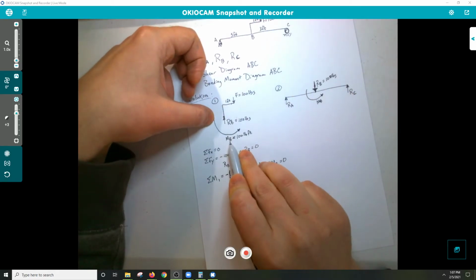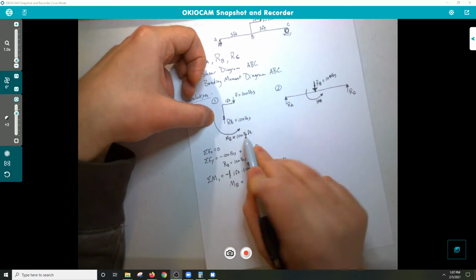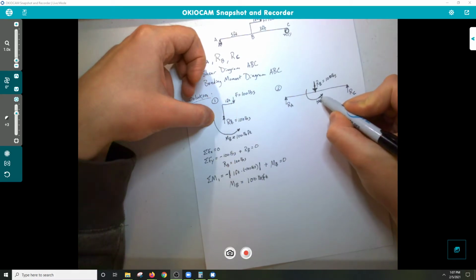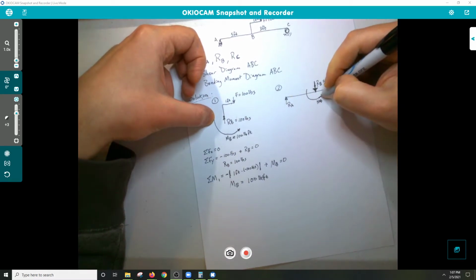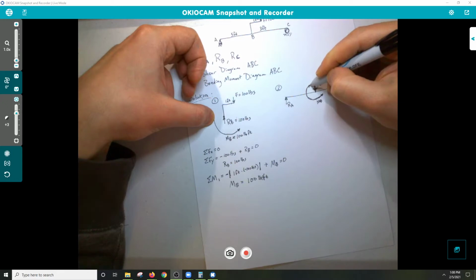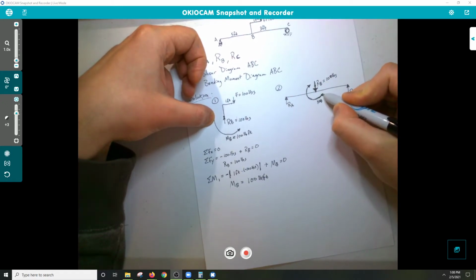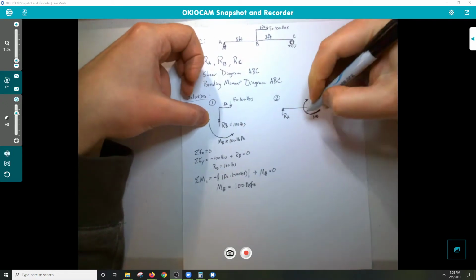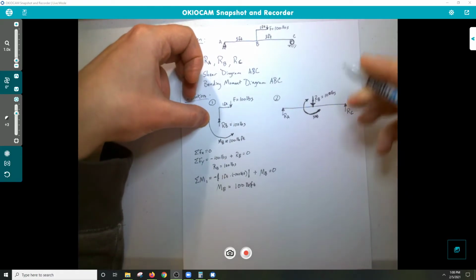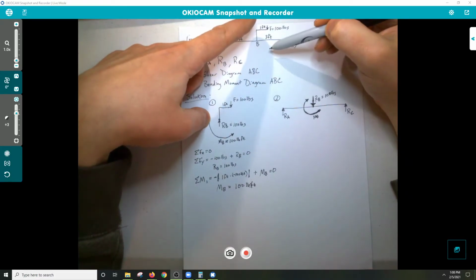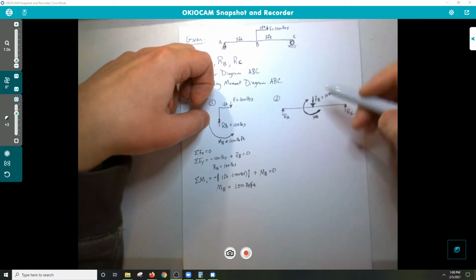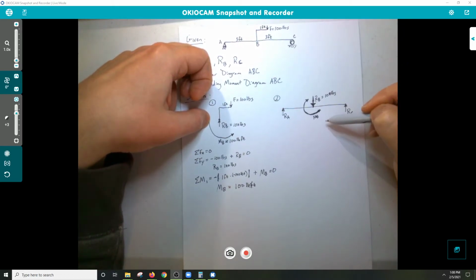So the bending moment here, again, is equal but opposite, so this has to swap directions. It makes sense if you think about the direction that the F force is going to cause this to spin. If we look at how that's going to want to make this pivot, it's going to cause a moment here at B, right?